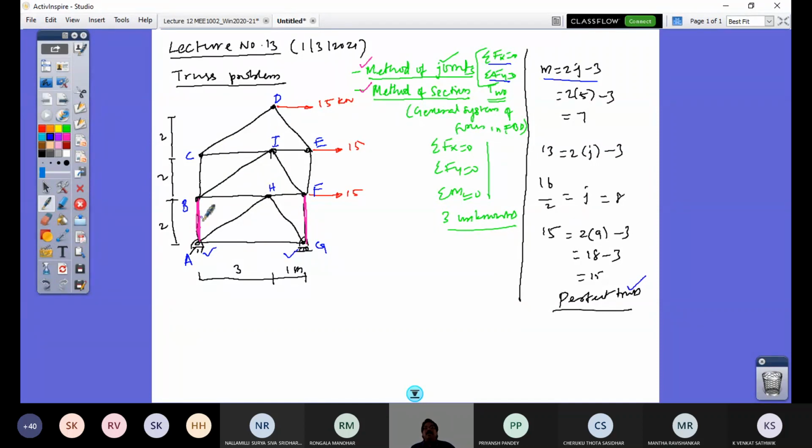So what I should do is cut this truss into two parts. The cutting of the truss can be by a straight plane, by a straight line, or I can also use a curved plane. That is my choice. But I make it into two parts. That's very important. When I make the truss into two broken trusses, both should be under equilibrium, to ensure the entire truss equilibrium.